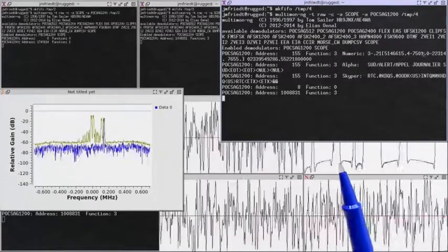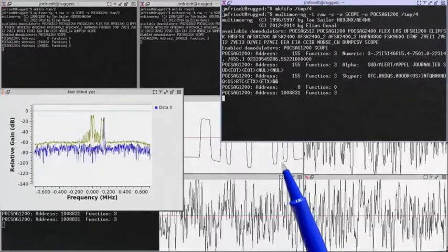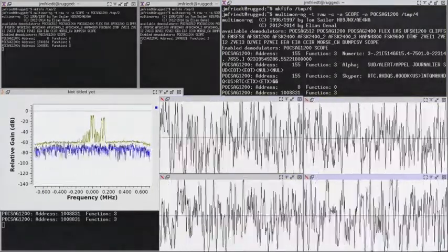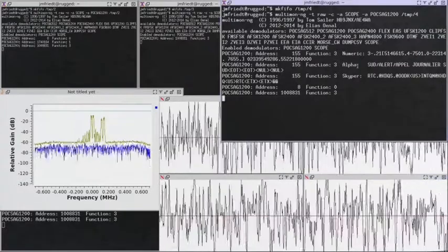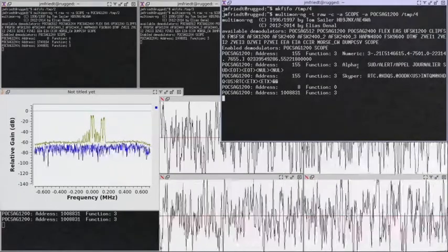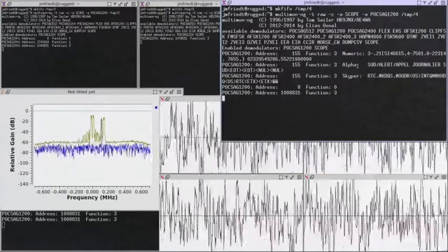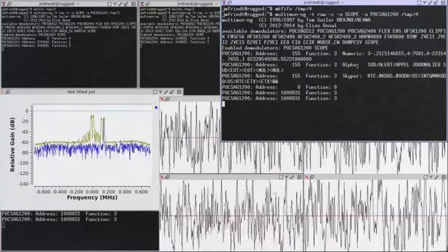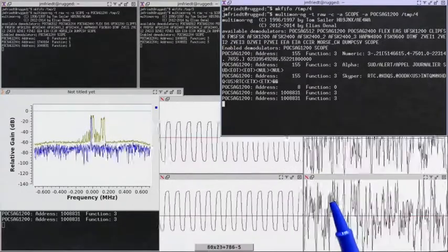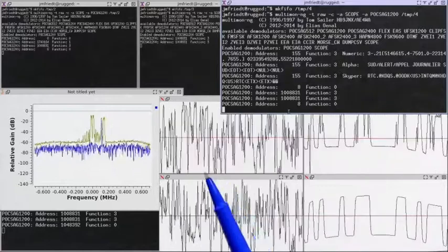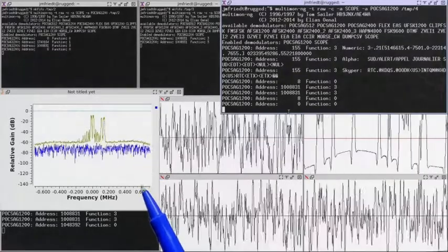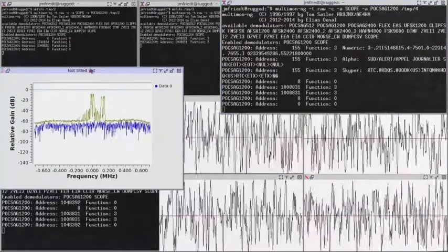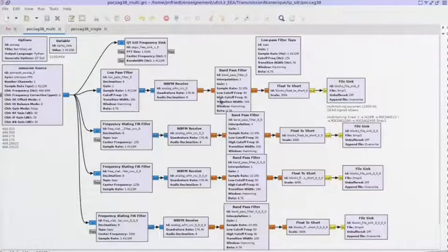Again, here is another message being transmitted, and here is a preamble followed by a message which is immediately decoded. So using this scheme, we see that we can simultaneously decode all 4 channels of POCSAG, only limited by the computational power of this computer. We see actually here that we have 4 copies of multimon-ng, and we have the spectrum analyzer. Each wideband FM demodulator is a thread by itself, so the computational load is becoming significant to run all these decodings.